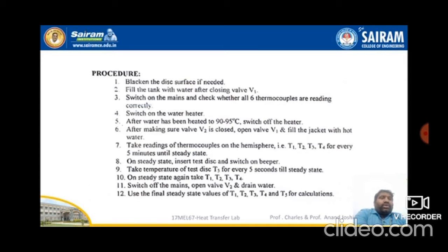After the water has been heated to 90 to 95 degrees centigrade, switch off the heater. Making sure valve V2 is closed, open valve V1 and fill the jacket with the hot water.